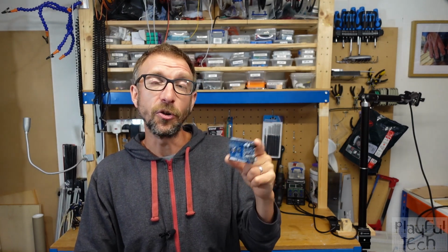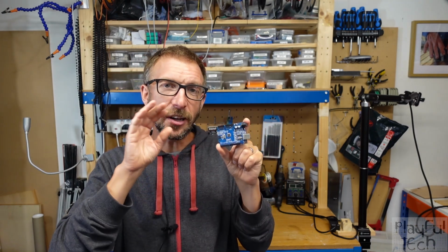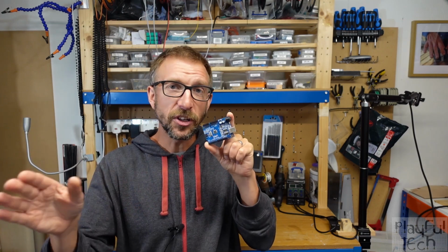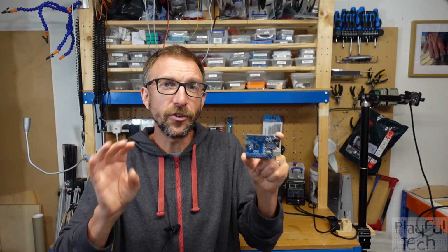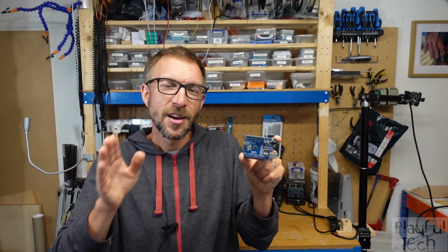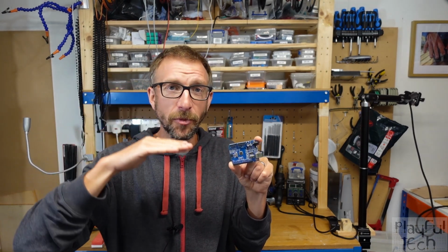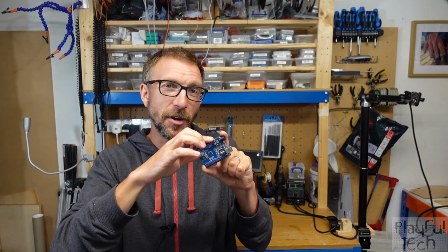Instead, what they do normally is something called pulse width modulation, or PWM. Now, PWM works by rapidly switching the digital output of a GPIO pin between high and low. And the frequency at which it changes between those values can be adjusted, but it's generally several thousand times a second, so it's very fast. And by varying the proportion of time spent in the high state compared to the time spent in the low state, which is something called the duty cycle, that adjusts the average voltage at that GPIO pin over a period of time.